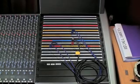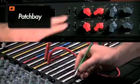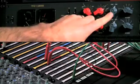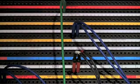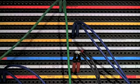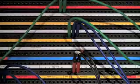Although they can sometimes seem confusing, patchbays are a really efficient and flexible way of connecting equipment in the studio. They are usually used to route signals between outboard equipment and mixing consoles, or these days direct to your DAW via hardware inserts. The idea behind the patchbay is to allow you to access all of the input and output options in your studio in one location. This eliminates the need to crawl around the floor trying to get to the rear of your rack equipment. For smaller setups, a patchbay may be overkill unless the equipment is permanently set up in an inconvenient location.